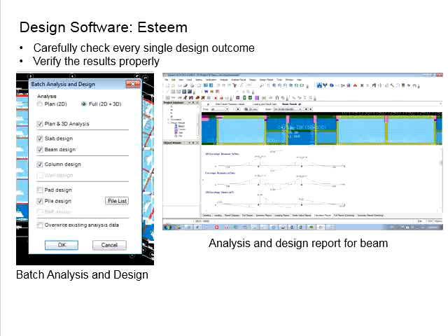The loads acting onto the member should theoretically have some relation with the coverage in terms of the area, as normally we apply the load on the basis of load per unit area. This at least will help you to have an idea whether your model result is correct.